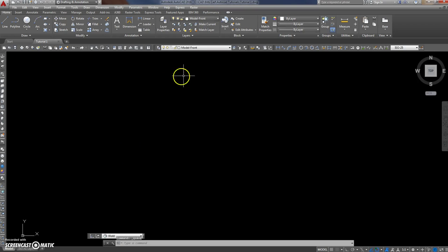Okay, save. So I've saved that drawing, and you can tell up the top there it says tutorial1.dwg, so it's saved. So now we'll try drawing a footplate, which is just a rectangle. So rectangle, and it really doesn't matter where you start putting your first corner point, because it says specify first corner point. You have to keep looking down at this command line. I normally wouldn't bother with any of those other options. We'll cover all this sort of stuff at a later date.